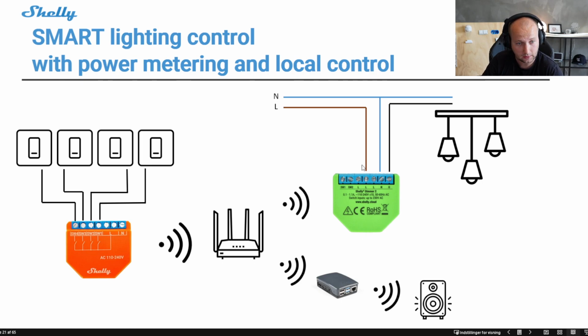And by the way, I forgot to mention that the Shelly dimmer also works without the neutral. If you have neutral, I would always recommend to use the neutral, but it also works without neutral if you have at least 8 watt connected power, or by using the bypass if you have less power connected.